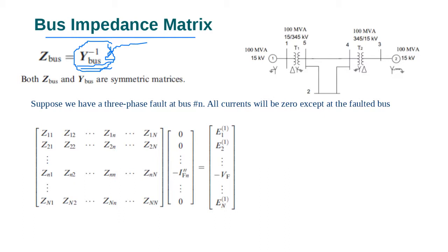All the impedance of the circuits are converted to admittances. And then we add the diagonal values. And of diagonal values, we put the negative sign. Bus 1 to bus 5, bus 1 to bus 3, and so on. The Y admittance matrix is sparse.